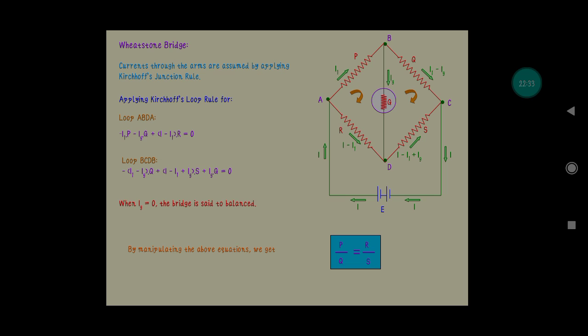Once you have a picture like this, it is a Wheatstone bridge. So in this Wheatstone bridge, if P by Q is equivalent to R by S, then the resistance in between you can remove, because the potential is the same, there is no current which flows through the galvanometer. This is what I am trying to tell. Is that clear so far?